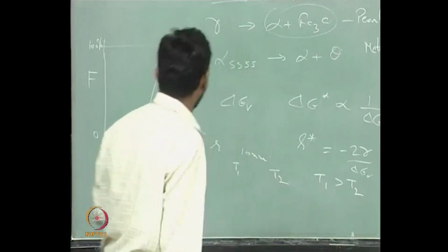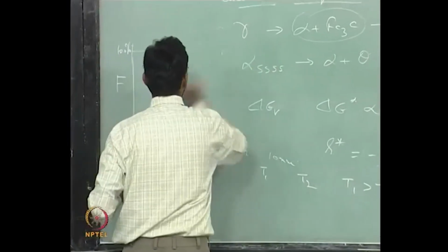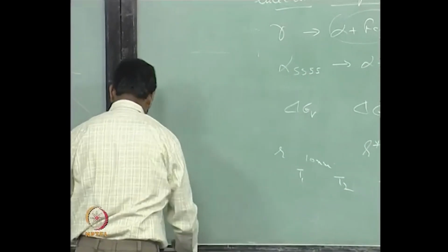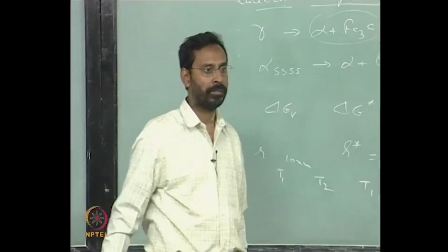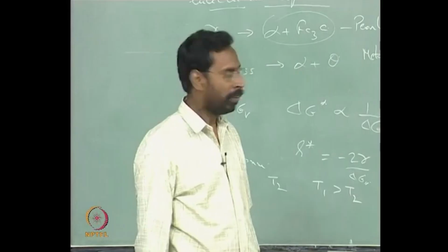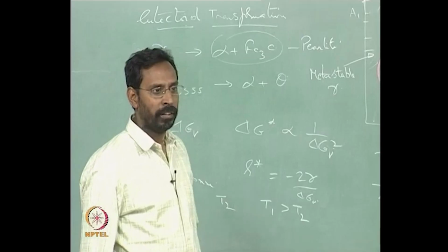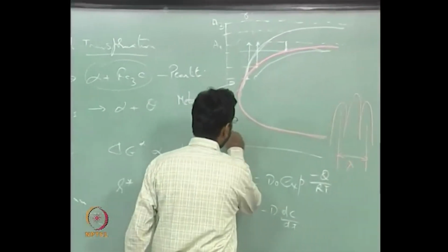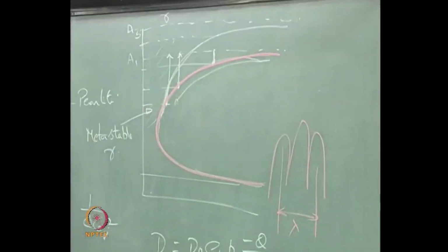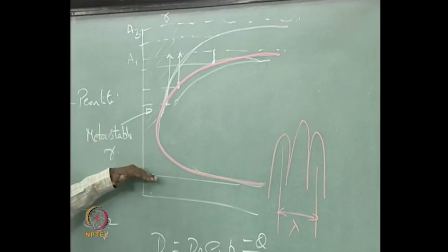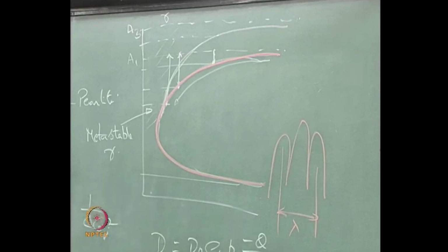For example, if you look at the upper bainite, in this shape of C curve, if I have a metastable structure such that I have got more vacancies, and where the diffusion is controlled by vacancies, correct, this will shift, obviously it will shift to the left, and this will extend up to the lower temperature, until you come to another structure which can form, in this particular case let us say martensite. So, you can keep on undercooling the austenite until you come to a stage where you can have a martensite transformation, which is a shear transformation.